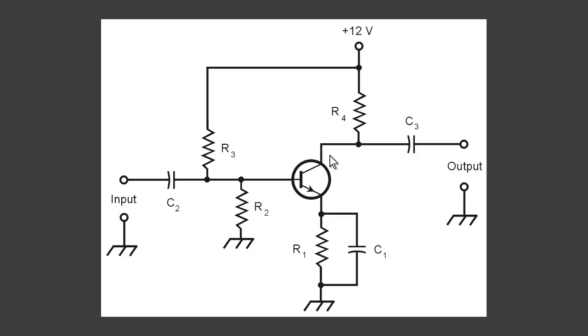Well, again, if we saturate a transistor, we can't make the collector current change by changing the input, unless the input is so large that it causes a slight change during part of the cycle. But we wouldn't want to operate a transistor in a state of saturation in order to try to get gain, so choice C is wrong.